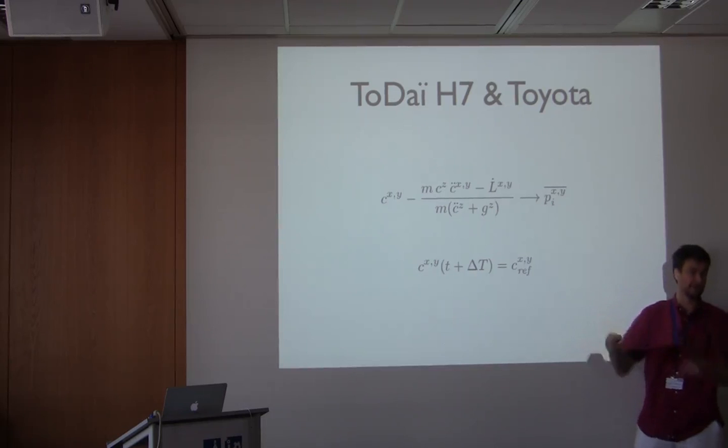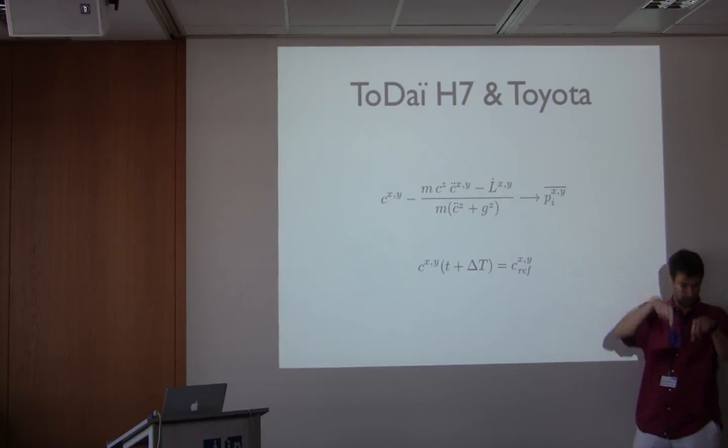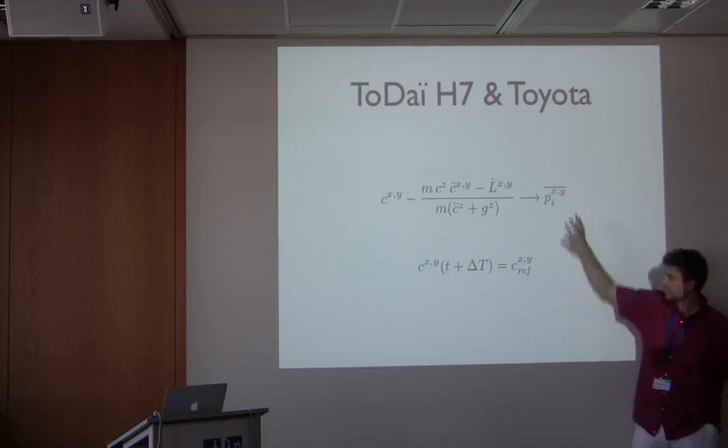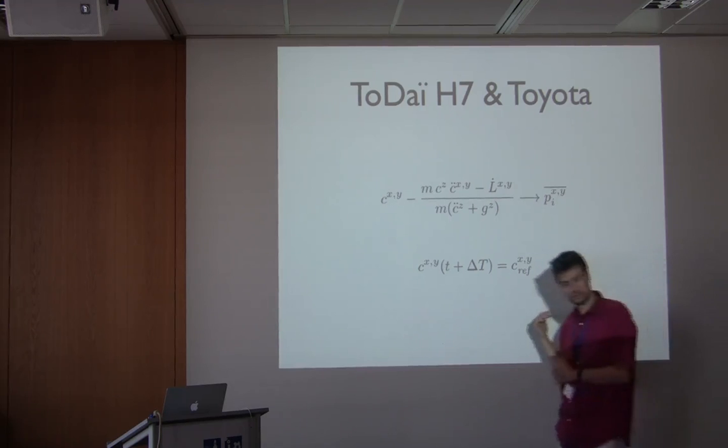So the footsteps are predefined, as before, and then you try to find a motion for which you put the center of pressure in the middle of the footsteps while imposing these constraints. And here we move back to this approximate capturability constraint. You only impose the position of the center of mass, but it works.